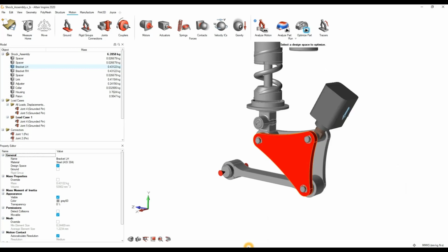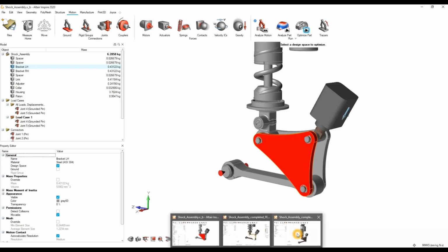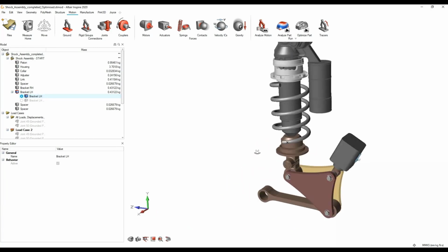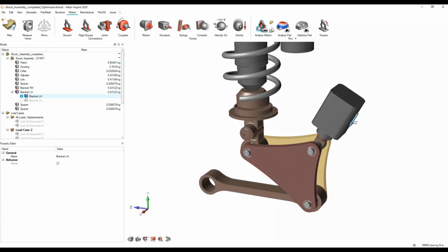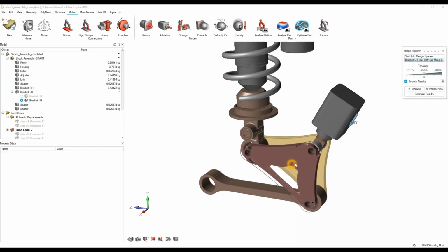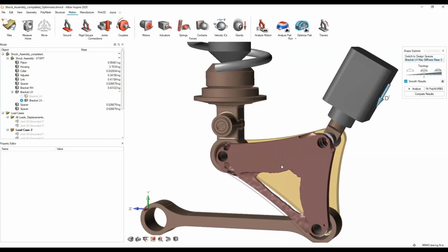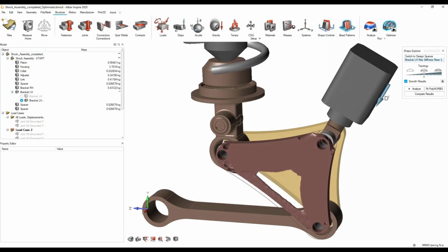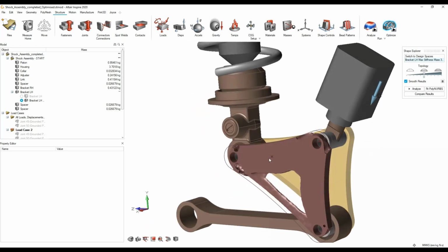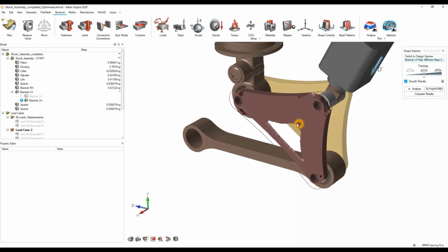Now I already have one that ran, so it only takes around 20 minutes to run. So you can see it's the same setup again, and once it's finished running, just by clicking on the truss button at the top here, you can see that this now gives you a new design. If you head back into structure, you can specify other manufacturing constraints as well, if you want to specify symmetry or draw direction, etc. But the Inspire structural analysis video should take you through that instead.